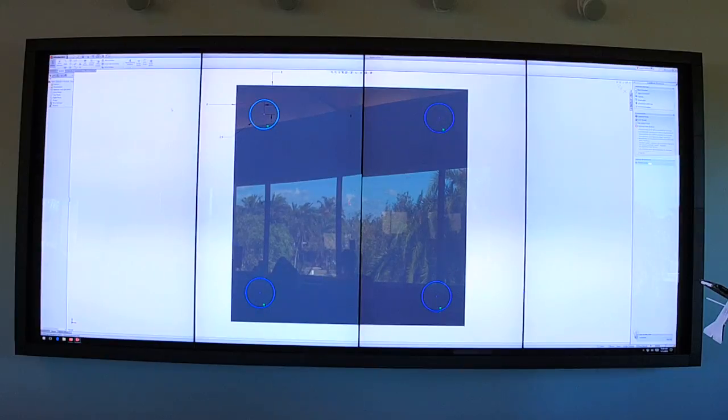Now that could be multiple holes, it could be thousands, it could be two, you can separate the distances between them, but it's a great way to get a specific group pattern that you might want for it. So now I've got that, I'd say, right, I've got my drawing, what am I going to do with it? I'm going to extrude those, I'm going to make them pillars, or I'm going to cut in. So right now I want to cut holes on this. So I'm going to go to the extrude cut section.